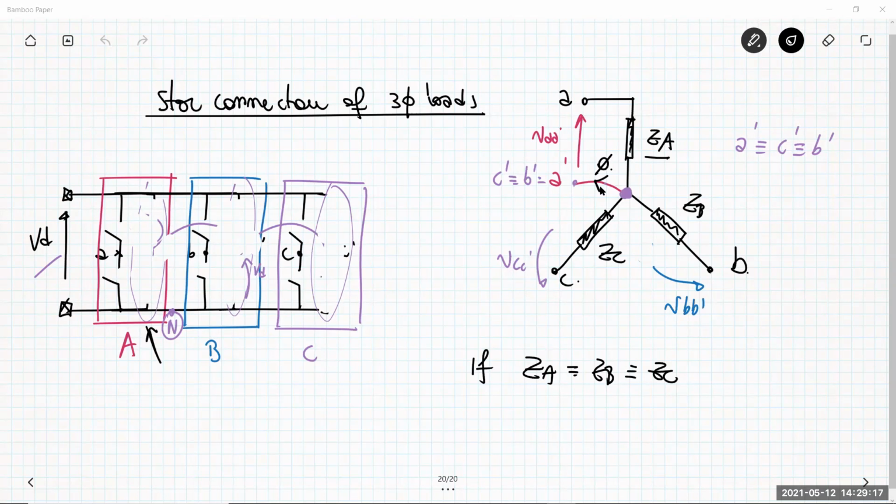Three-phase loads are constructed to be symmetrical and equal between them, so this is the standard situation. When a non-null current flows from that node, it means that something dangerous can happen, something is occurring. So the standard nominal situation is that the loads are always the same. You have an equilibrium, so no current flows in that case. Of course, there are situations where this happens, so we have to manage them differently from what I said now.